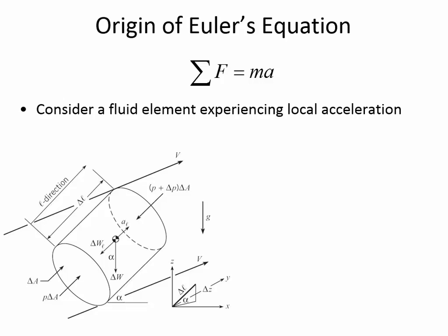In Euler's equation, we are going to account for the weight of a fluid element, and we won't neglect gravity. Euler's equation will enable us to find the incremental change in pressure due to acceleration in any direction. This is just picking the L direction as an illustration that the acceleration could occur in really any orientation.